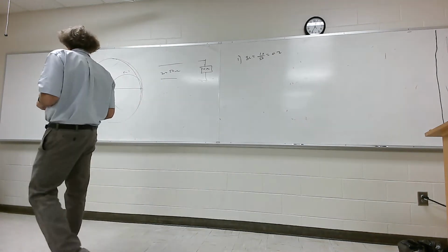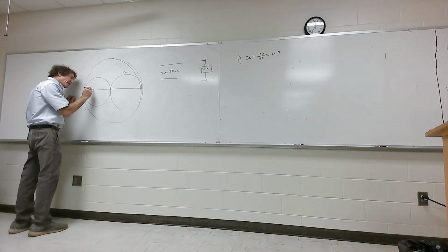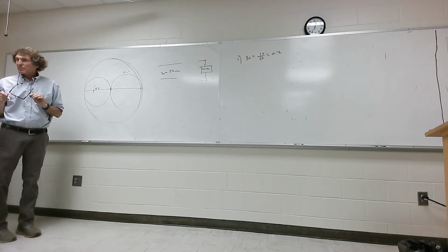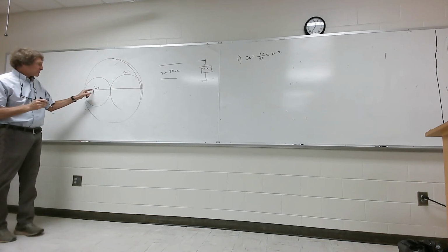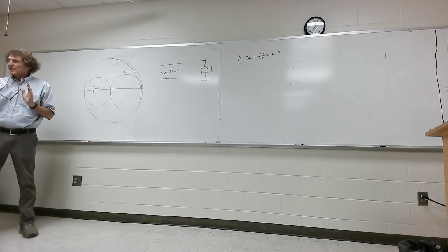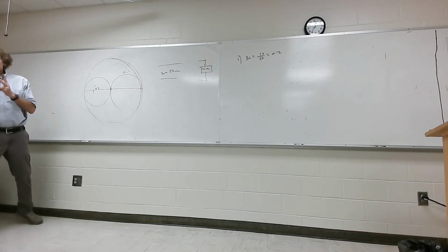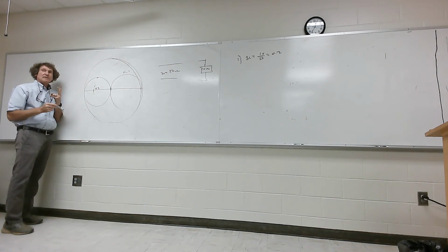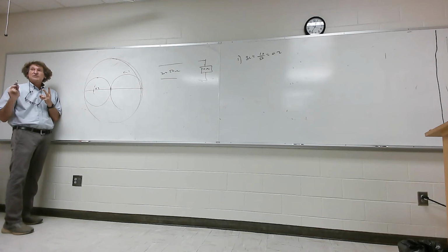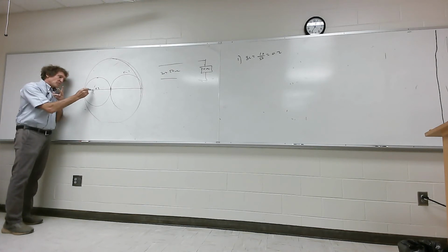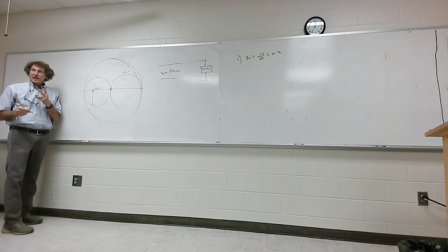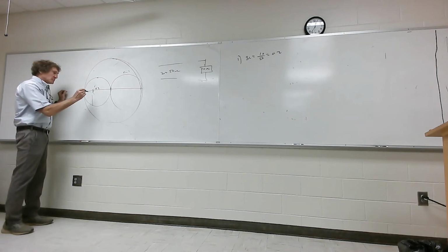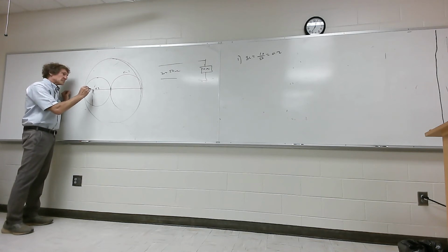So now we plot it. Well, 0.2 is right about here. Can you all see that, class? Just make sure you can locate that. That's 0.2, and it's inside the rotated circle. Now we have two choices. Remember, this is impedance. We can move this way, which would be adding a plus J impedance, which is an inductor in series. Follow me? That's preferred. Or you can move this way and get to that circle by adding a capacitor in series, that's minus J. I always say to use an inductor in series if at all possible. So I'm going to move from there to there.